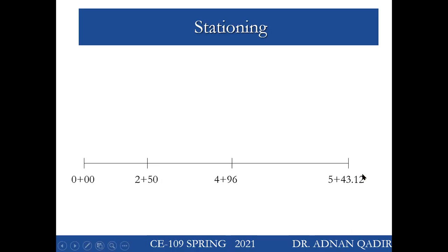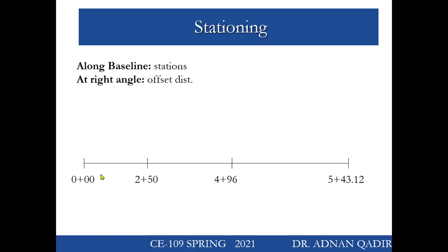You must be wondering, sometimes you see these, there are plus and there are three distances, 3 units. If you have 3 digits after the plus, then it's meter, and this is kilometer. So maybe you have taken 1 kilometer and 250 meters if you have got 3 digits after this point.